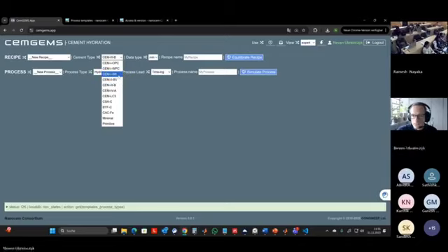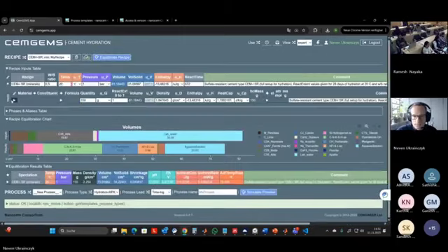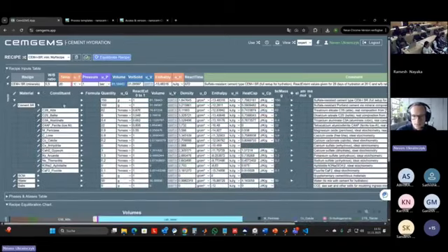Sulfate resistance. So this one has less aluminates, less C3A. And it's sulfate resistant because of the aluminates, you know, the delayed ettringite formation. If there is too much aluminates, then there is ettringite which expands and then cracks the system. You can see here we only have 0.4% of aluminates, but we have 22% of C4AF. Usually this is like 9% of aluminates in cement. So this has a very low percentage of C3A.